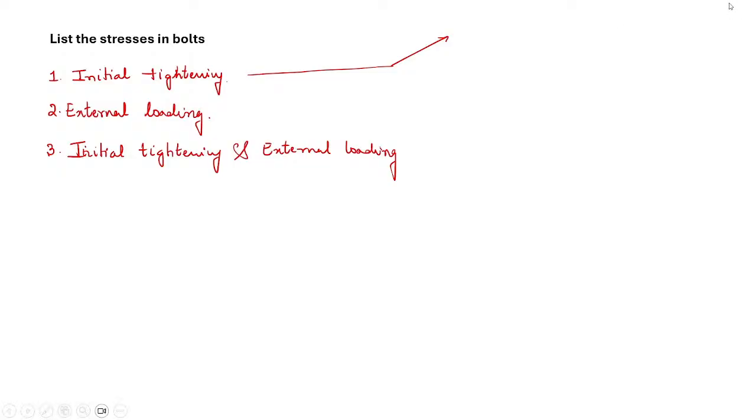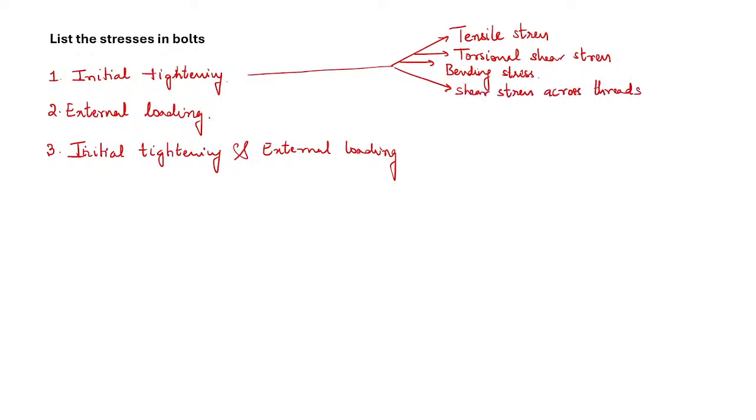The first one is tensile stress, the second one is torsional shear stress, third is bending stress, fourth is shear stress across the threads, and fifth is crushing stress.